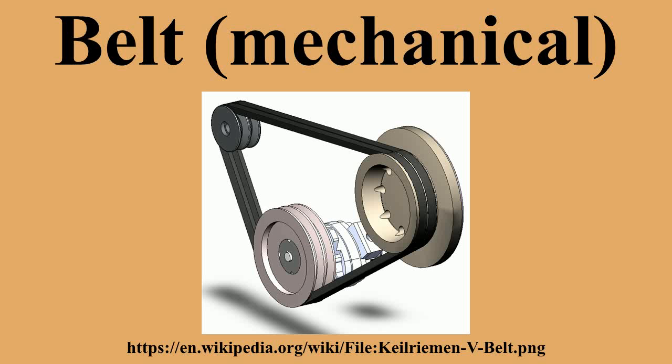Industrial belts are usually reinforced rubber but sometimes leather types. Non-leather, non-reinforced belts can only be used in light applications. The pitch line is the line between the inner and outer surfaces that is neither subject to tension or compression. It is midway through the surfaces in film and flat belts and dependent on cross-sectional shape and size in timing and V-belts. Calculating pitch diameter is an engineering task and is beyond the scope of this article.